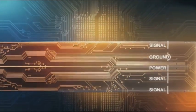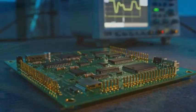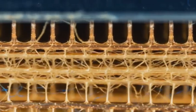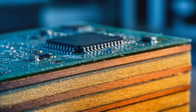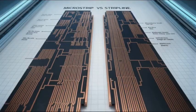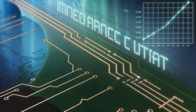A typical 4-layer board stacks signal, ground, power, then signal again. Internal layers usually handle power and ground, separated by dielectric materials like FR4. The outer layers carry signal traces, with core thickness typically larger than prepreg layers, influencing EMC performance. Common PCB geometries include microstrips, traces over a ground plane, and strip lines, traces between two planes. Trace dimensions and dielectric properties directly affect impedance, critical for EMC management.